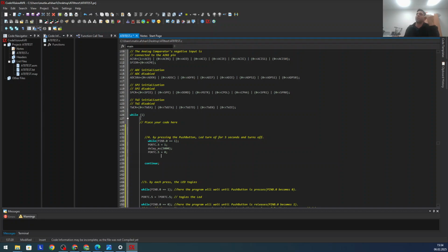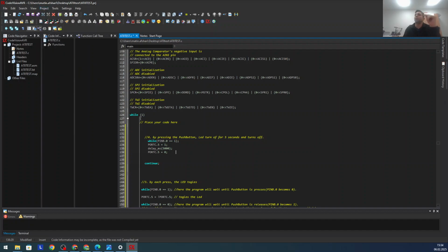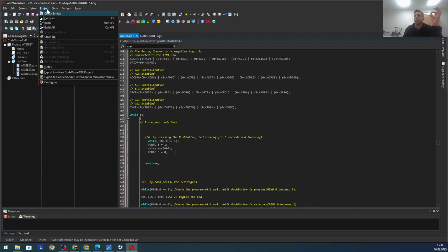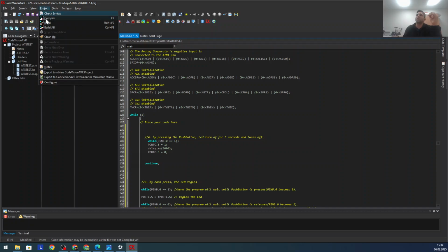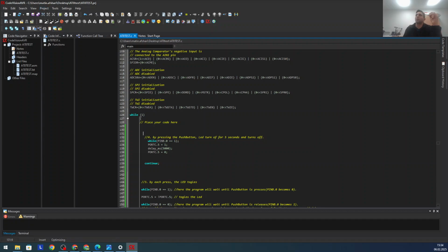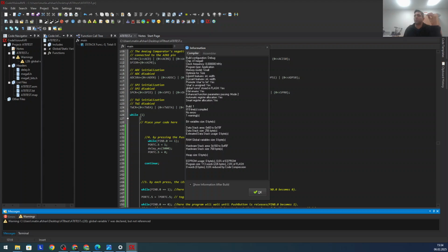You will do this on the microchip, and every time that you do any of them, you have to build the project. For example, in the other video, my picture was in this corner, so you could not see how I built the project. Here, I wrote this task. I would go to Project, and Build All. After I press that, this kind of window comes up, and it has given me a warning. 0 errors, it should be 0.